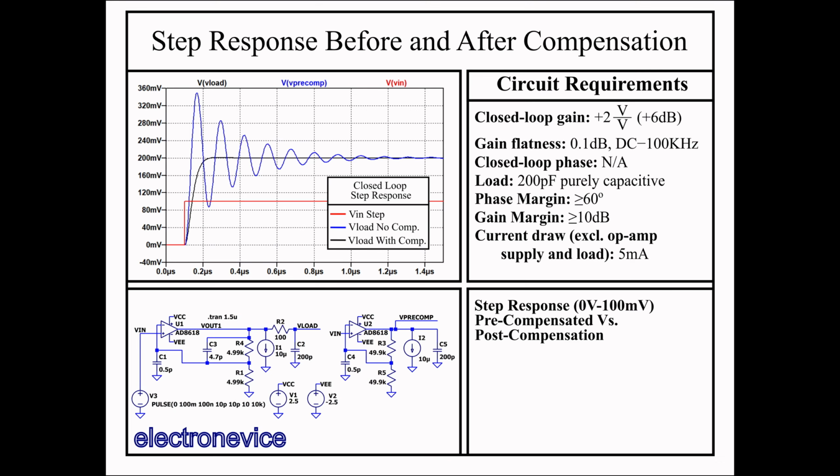I would like to reiterate that in general, op-amp SPICE models are not complete, and in particular, output resistance and input capacitance are often not very accurate. So if you're using a SPICE model to simulate your circuit, I recommend testing it for appropriate output resistance and input capacitance and modifying the circuit to reflect the datasheet rather than just assuming the SPICE model will properly account for these parameters, and doing multiple simulations for minimum and maximum value if necessary.